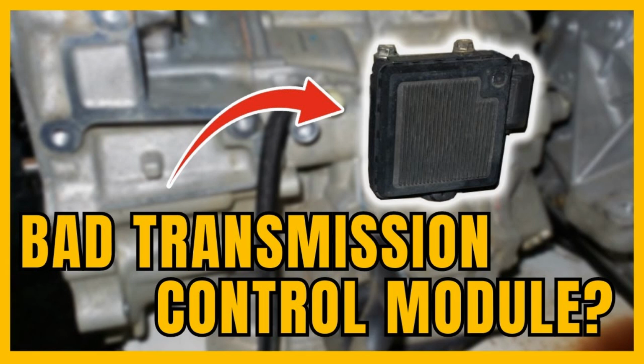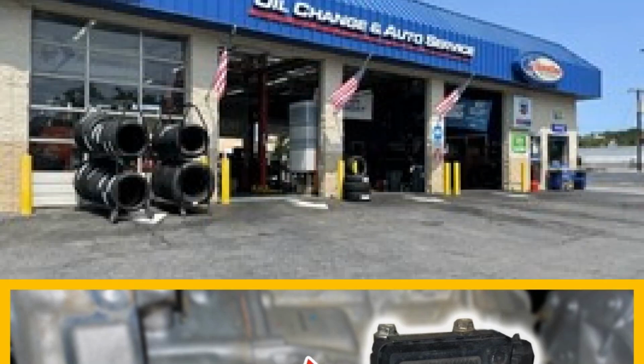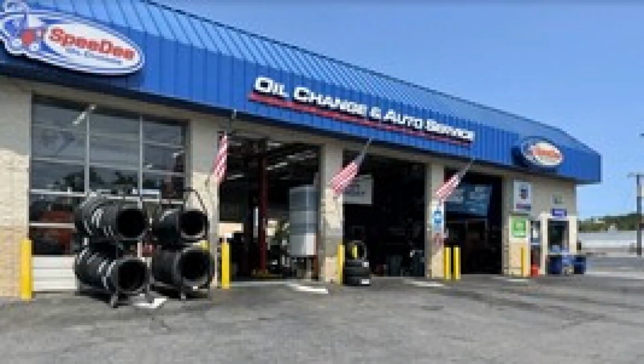How to eliminate or clear fault code P07A6. Some suggested steps for troubleshooting and correcting fault code P07A6. Change the ATF fluid and filter. Top up the transmission fluid to the required level. Flush to clean the transmission's internal ducts. Check the wiring and rectify any faults found. Troubleshoot mechanical faults inside the transmission. Check the connectors and wiring. Flashing or replacing the PCM or TCM.